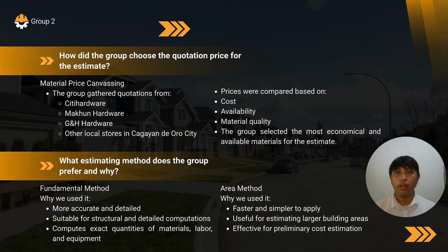And for the method used, we prefer the fundamental method for structural and detailed computations. We use this method because it is highly accurate and computes the exact quantities of materials, labor, and equipment needed. We also utilize the area method for preliminary cost estimation because this approach is faster and simpler to apply, making it particularly useful for estimating larger building areas.